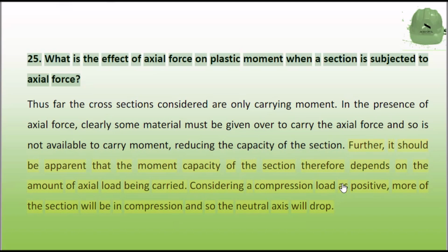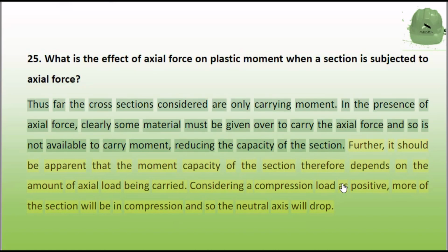What is the effect of axial force on plastic moment when a section is subjected to axial force? Thus far the cross-sections considered are only carrying moment. In the presence of axial force, clearly some material must be given over to carry the axial force and so is not available to carry moment, reducing the capacity of the section.